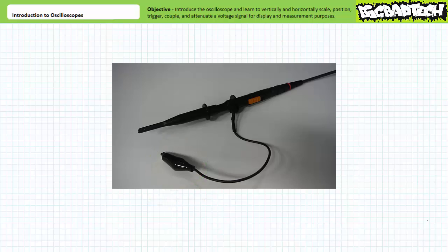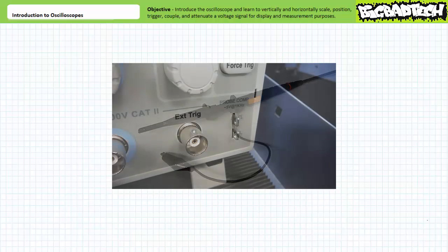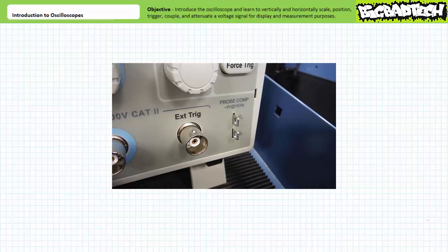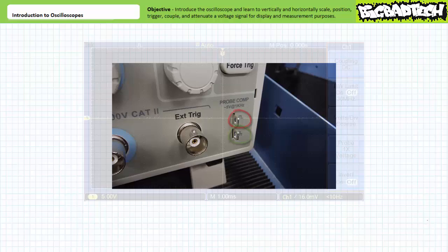which, as we'll learn in later applications, may be a total deal breaker. For now, just consider the grabber as equivalent of the red lead of a voltmeter and the alligator clip as equivalent to the black. The caveat being that this black lead is always directly connected to ground. The test point conveniently features both the test signal output and a ground reference for test purposes.